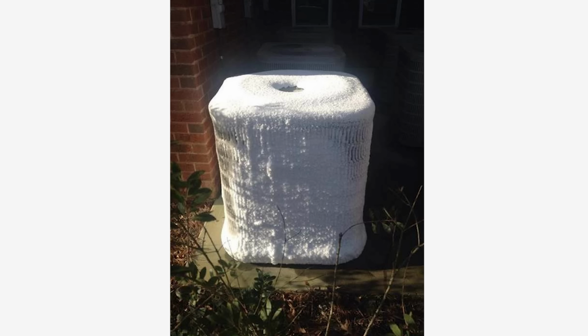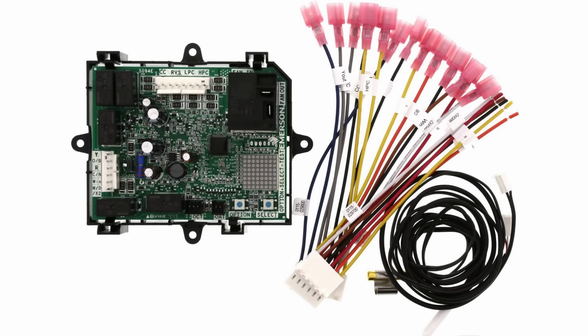They usually use sensors mounted on the coil as well as an air sensor. It's the most common strategy here. We're showing an Emerson board, which is an aftermarket, very common board used to deal with defrost.